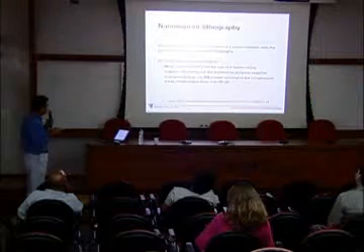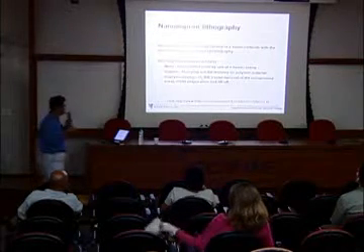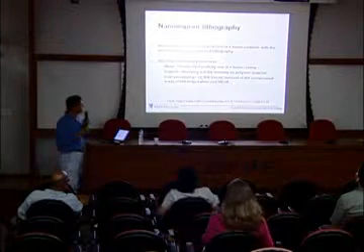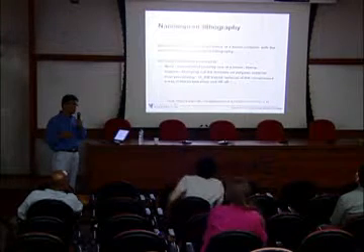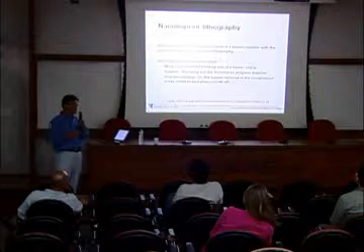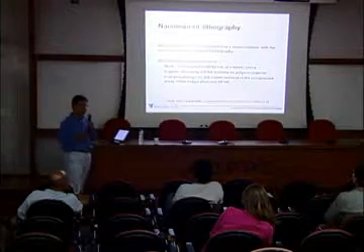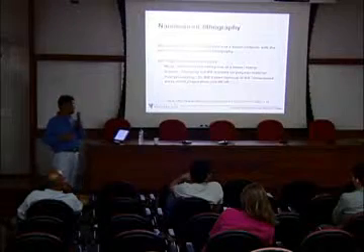The major steps for this nano imprint lithography are 3 steps. First of all, we need to make a mold. The mold usually is a very hard material on silicon. So we can place an order to make this kind of mold in a wafer. If we want a pattern size of 100 nanometer in a wafer, then it's about $4,000 or $5,000. It's more expensive than micro contact printing because of the small size. Those small features will be made by electron beam lithography.